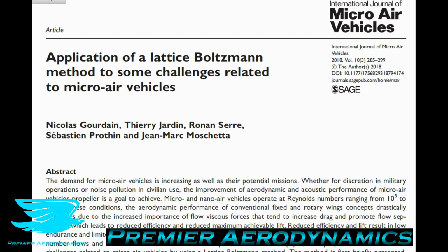So to speed this up, you go, okay, I'm going to use 4 cores. I'm going to double that again. But instead of going to 6 hours, it might take 8 hours. So again, you only get a slight reduction. And the further you go, the lesser reduction you get. So in my experience, once you get to about 2,000, 3,000 cores, you don't get any more benefit in terms of time for solving.